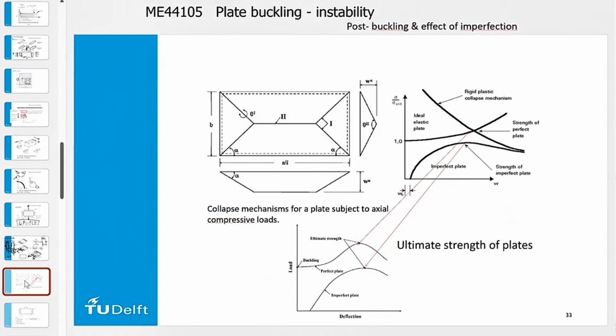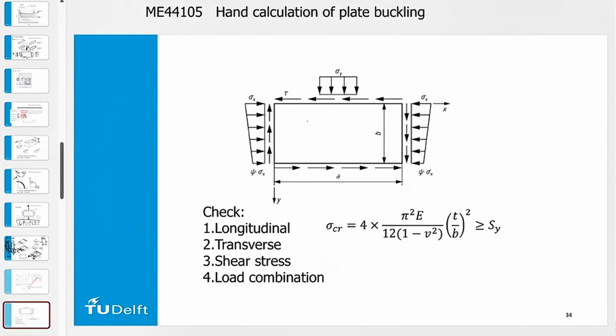So if we take that into account, then you have a modification of your curve. If we also take into account the imperfection of the initial plate, we get some modification curve. So that is different between different standards. This is something you do have for crane structure, since you have a specific wheel load on top of a plate. They have a modification if we have a stress concentration, not a concentrated load, but then over a smaller area. So there's a correction factor for that.